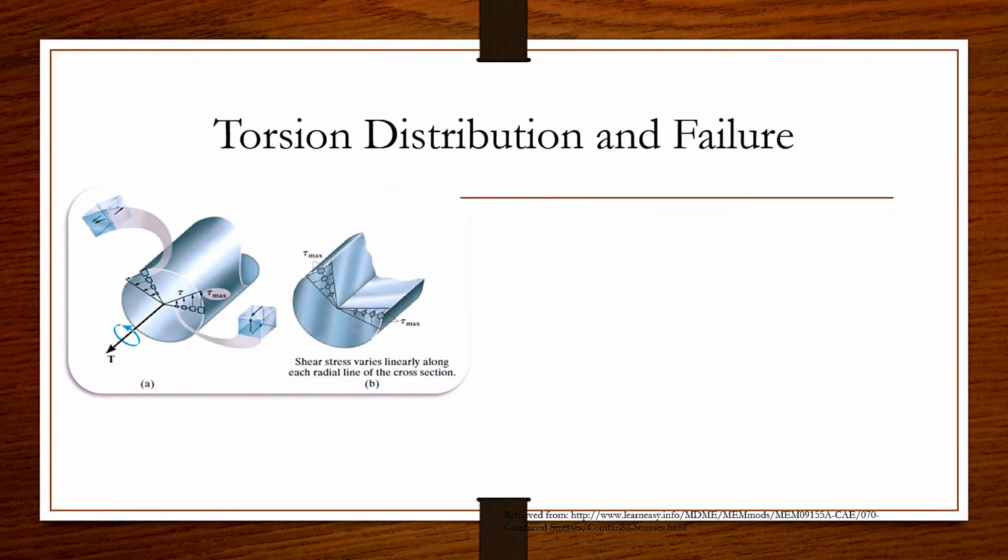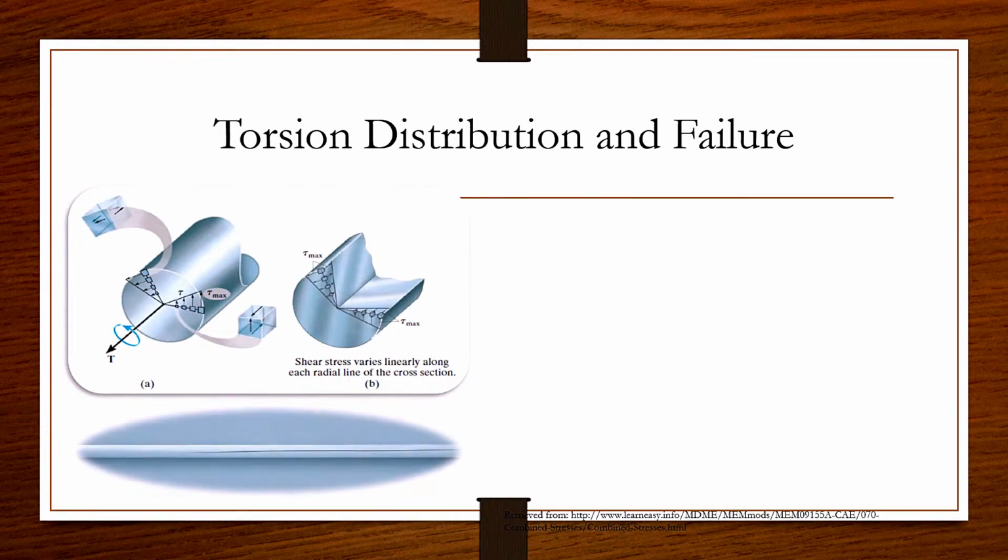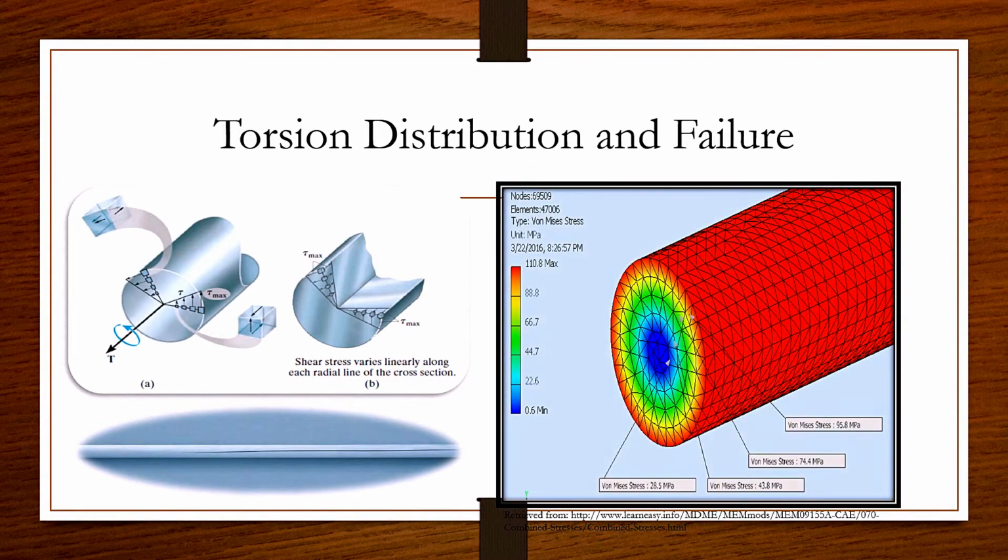Stress can be visualized increasing as we move towards the edge of the pipe. At small distances of x into the pipe, the stress distribution follows the same pattern and applies to the adjacent faces as seen on the picture as well. Once the maximum shear stress has been overcome, a crack will form along the longitudinal axis of the rod and cut right through towards the center of the shaft, as seen in the following picture below. Our software would show you the stress distribution that the shaft can handle throughout the entire rod, and my associate Joe will show a sample of how the software will calculate the stresses at any given point.